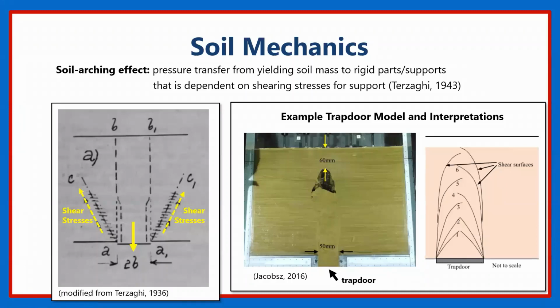It's like a door that opens, and so the trapdoor serves as a void roof, if you will. This vertical structure you see is the soil arching in effect. We can use that to interpret different types of shear surfaces or failure planes. And as you can see, the structure gets taller, which is that vertical progression I was talking about before.